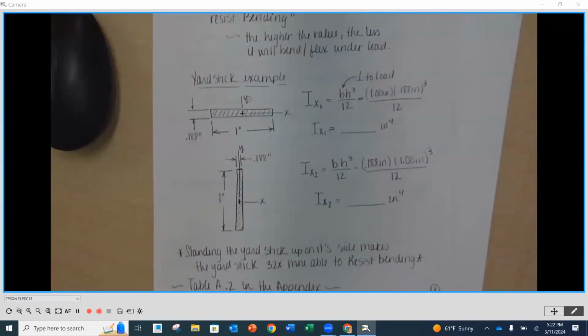Okay. If you go down in the basement of your house, and if you haven't remodeled your basement, you can look up and see 2x12s, okay? And those 2x12s are standing up so that the vertical dimension is the tall way, not laying flat. It would be really bad if it was laying flat, because then your floors would want to flex, okay?